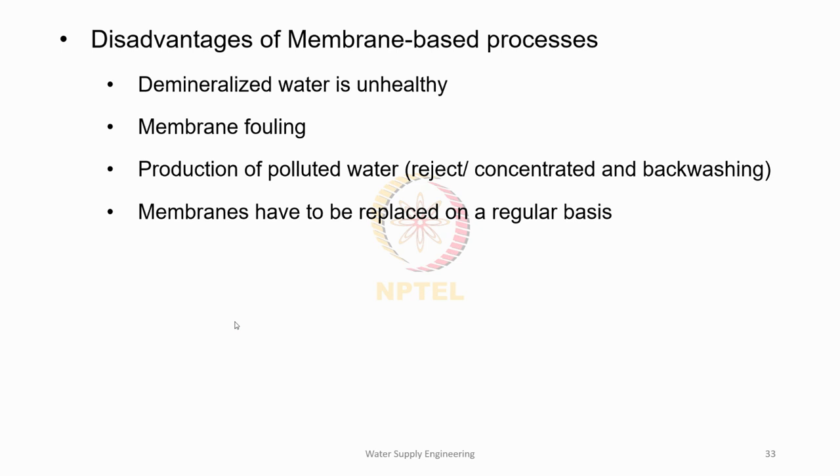Another problem is that of membrane fouling. So the membranes that are used for the treatment process will frequently get clogged or fouled and makes it necessary to replace them on a regular basis. Another issue is a good amount of water is generated as polluted water through reject, backwashing, or concentrating the sample.